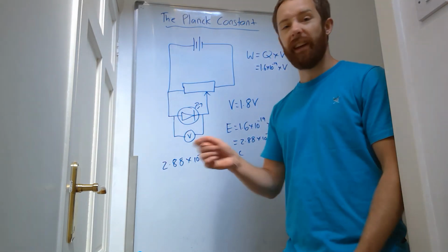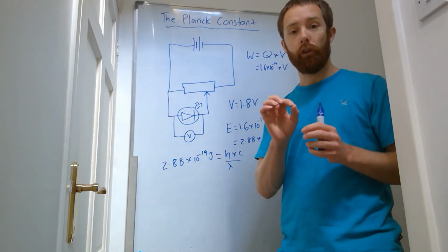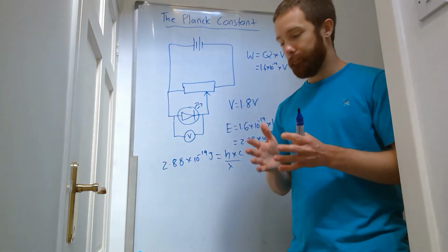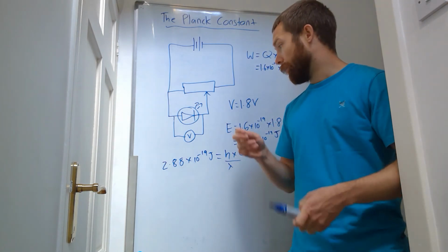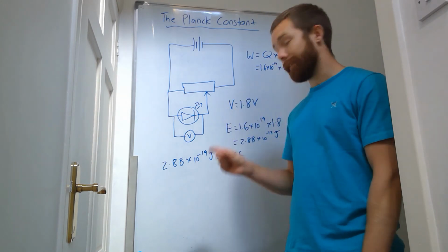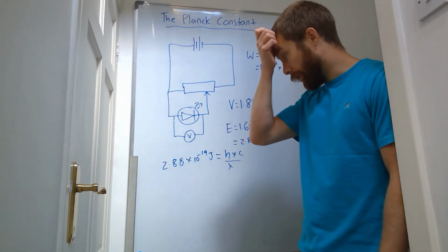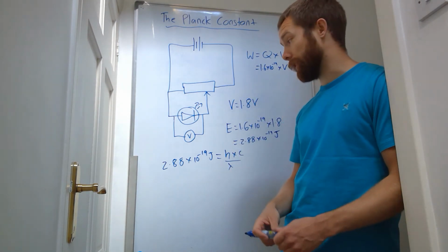This is something that you would find from the manufacturer. It would either say it on the LED, or more likely on the packet, or you could just look up the LEDs, the ones we use in the lessons that I teach. We go to the manufacturer, look up the code, and it will say what the wavelength is. It will even say what the uncertainty might be, so you could do an uncertainty calculation with it.